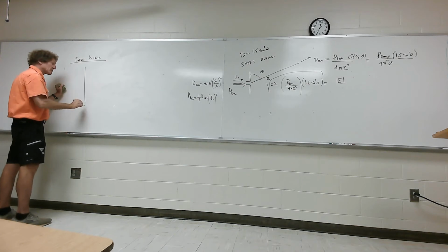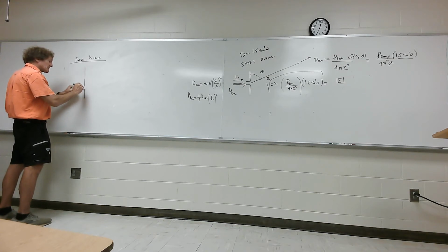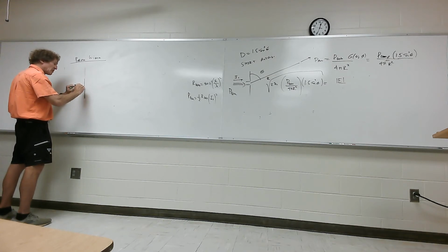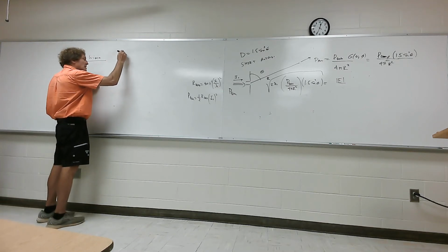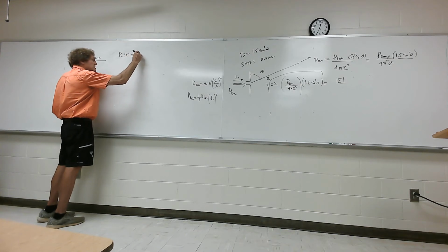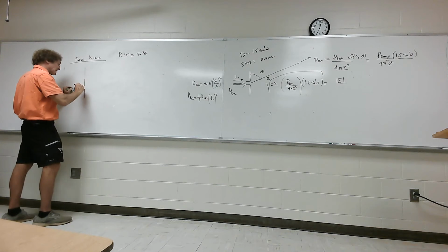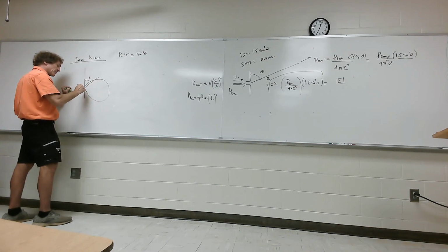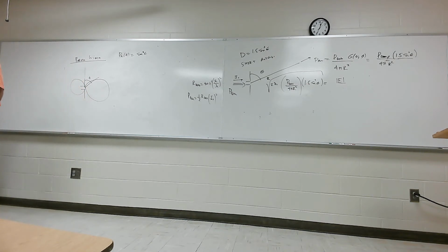Let me explain this a little better. If my antenna is a short dipole and it's going this way, and I plotted the normalized power pattern, this is sine squared theta. Well, if I plotted sine squared theta, and this would be the angle theta, then I would get this. This would be in a polar plot. Y'all follow me on this class?